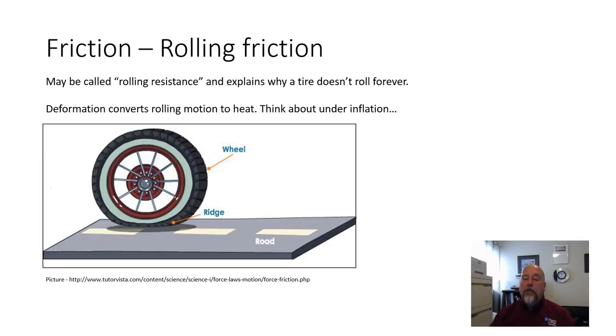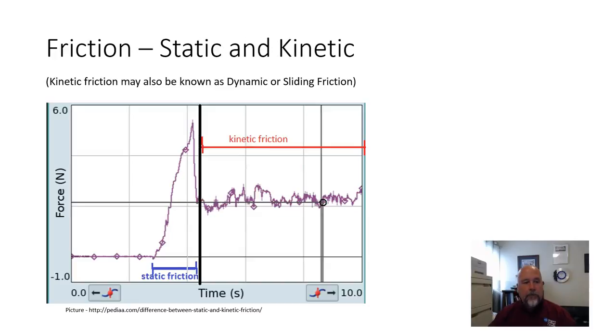Generally speaking, and this is a bit of a blanket statement, the more air you put in a tire, the easier it will roll, and the less heat it will generate because the rubber in the sidewall and the cords and the structure of the tire isn't flexing as much. Conversely, if the tire is underinflated, it flexes a lot, and that flexing will generate heat.